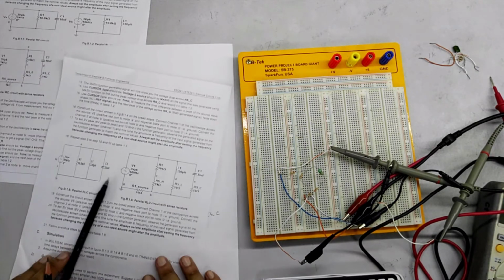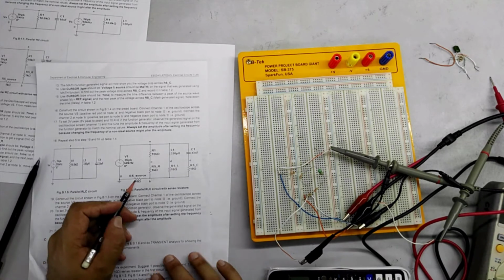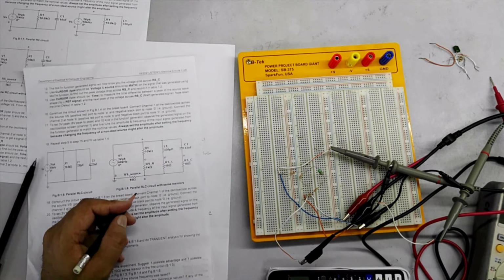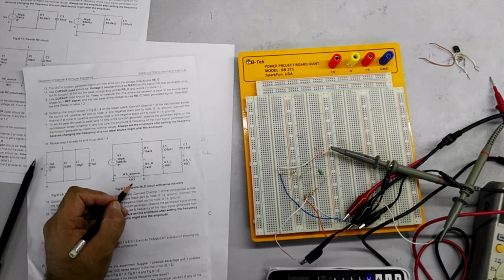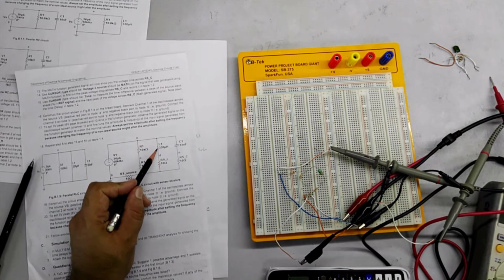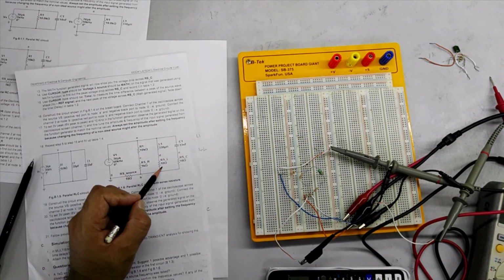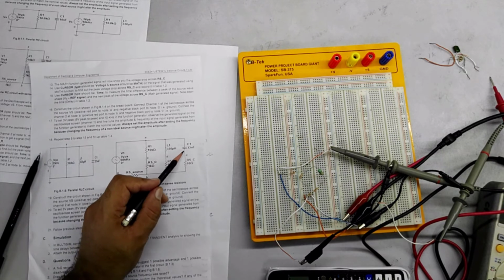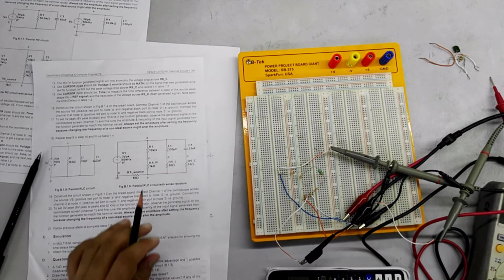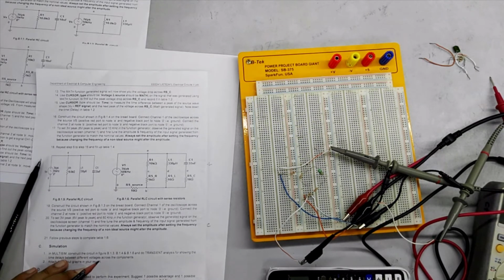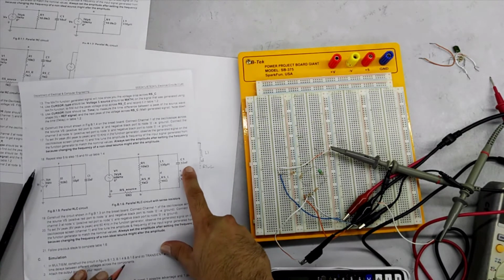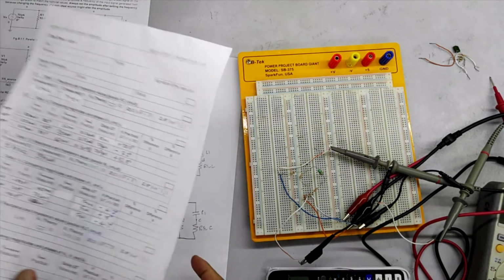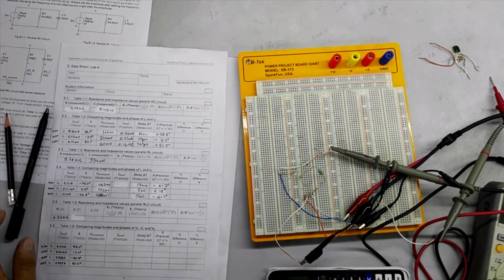So if we look at the circuit, the sense resistance for the source is 10 ohm now. The sense resistor for the inductor is 10 ohms, and that of the capacitor is 10 ohms, and the capacitor is 33 nanofarad. Before constructing the circuit, we should record the practical value of this capacitor of 33 nanofarad.